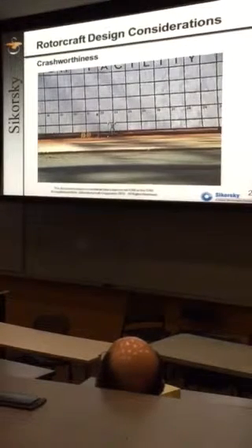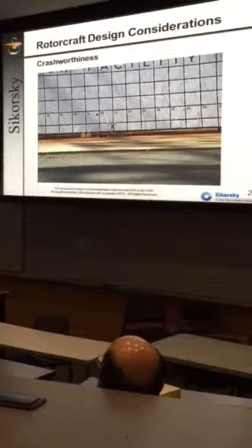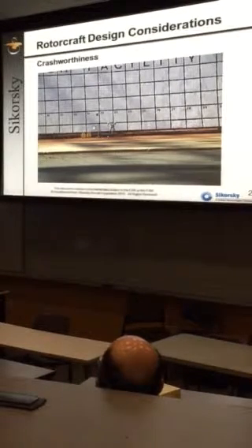Another thing we have to design for is crashworthiness. We talked about bringing people home every time, everywhere, every time. One of the big design factors for rotorcraft is it has to survive an impact, typically on the order of 35 to 42 feet per second, which is a crash condition. We have to design it so the occupants survive that kind of impact. And one of the ways we do that is with a crash test,